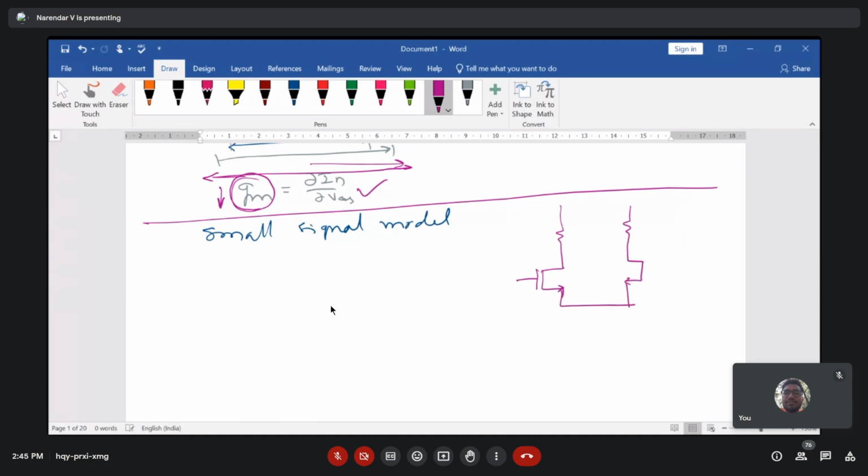M1 transistor and M2 transistor, and here we are talking about small signal. So small signal definitely has two components. One is DC to bias your transistor, and then V input one, or you can call it VG1, right, connected to ground. And then definitely here we have some current called ISS connected to ground, and this one is referred to as positive and negative. This is VCM plus VG2.